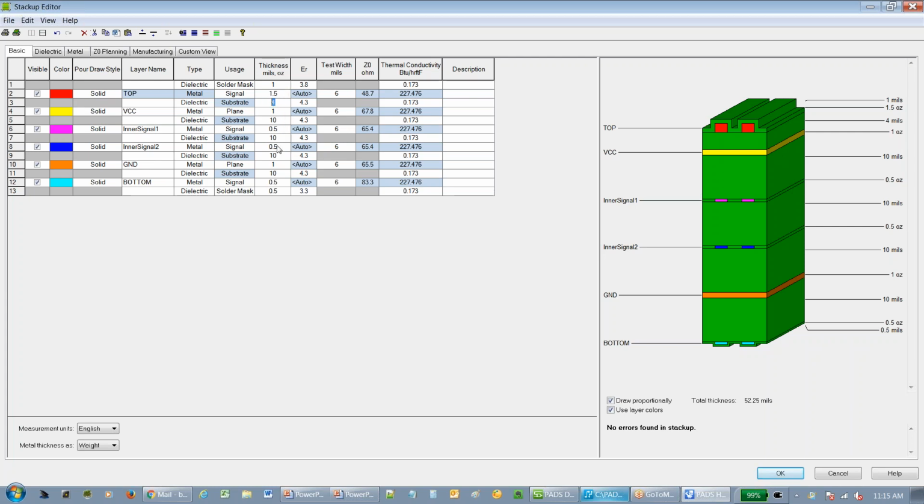All right. Something else to think about in design is this is a basic, simple 6-layer board stack-up, but one of the advantages of putting power planes in your board is actually using the planes as a way to control power supply noise. Okay. So yeah, you might want to do this for design, but you also may want to add 2 more power planes to the internal layers, especially if you're getting into higher frequency designs.